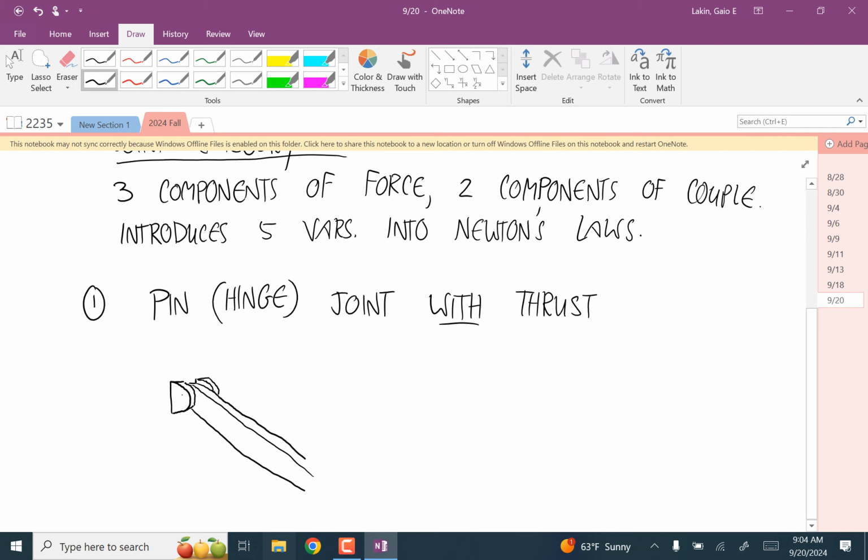Okay, and then the pin there. So this thing can rotate about its axis, and that's all it can do. Remember the last one we did, that pin kept it from translating anywhere in that plane, but without the flanges on the side, it was free to translate along the pin, along the axis. Now that's restricted too. Okay, so that's where the 5th variable comes in.